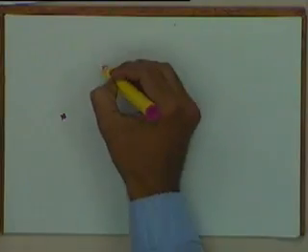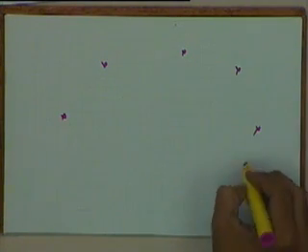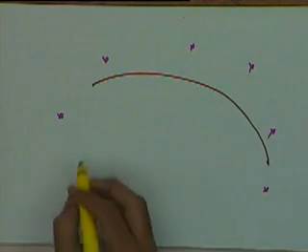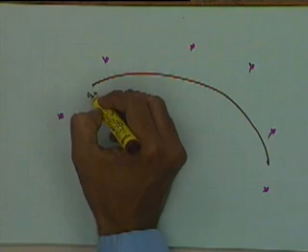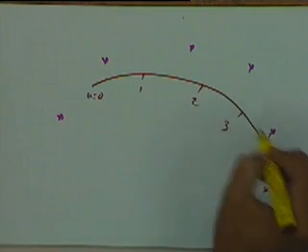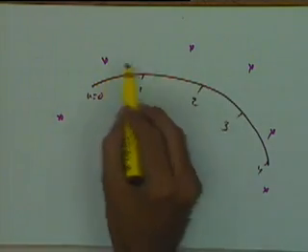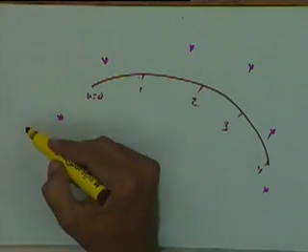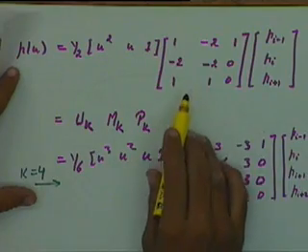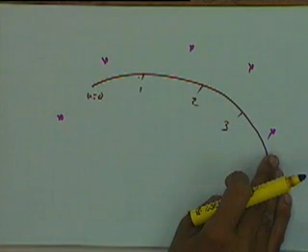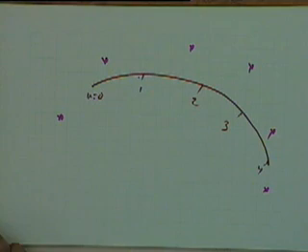That means if I have a set of points, the starting point of the curve is here, ending point is here, and the curve is like this. It doesn't start here, it doesn't end here. And I will get u equal to 0 here, 1, 2, 3 and maybe 4. This part of the curve will be a combination of these 3, this part of the curve will be a combination of these 3, and the combination will be given by this expression. That is why it is called periodic. That means the same function is continuing again. We will see some more details on periodic and non-periodic curves in the next class.